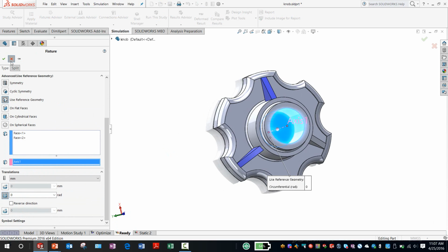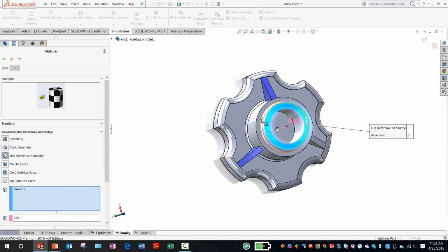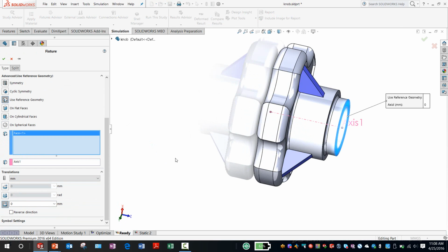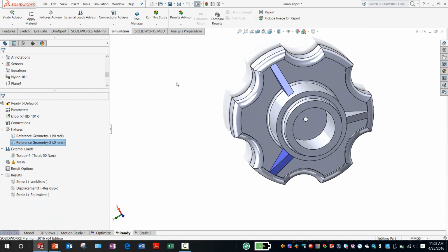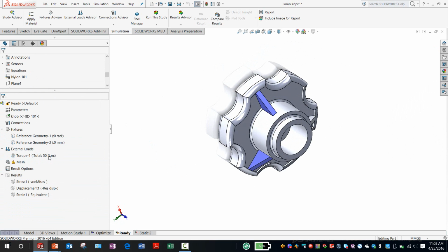You can see it here. Number two, similar thing, it is the bottom part of this cylinder. Again, this is restrained in the Z direction, and being restrained from not moving in the positive Z direction. So those two restraints or constraints have been given to this part. It cannot move in those directions.